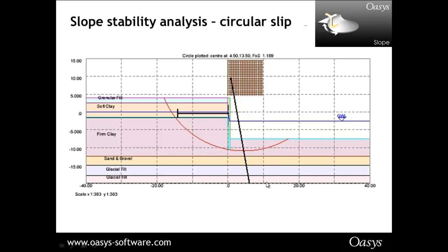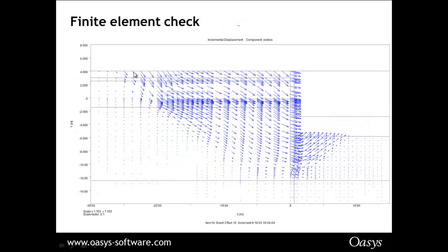And so this is why there was a failure of this particular retaining wall, or the dock wall. So a finite element analysis was run. I think you can maybe very faintly see the anchor, or the back of the anchor, here. And as you can see, this particular slip surface isn't perfectly circular.